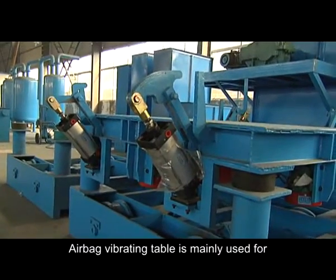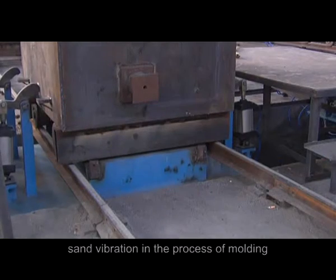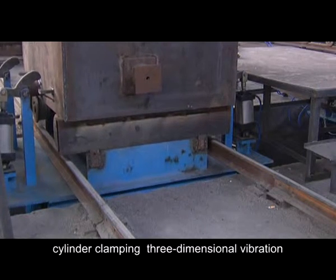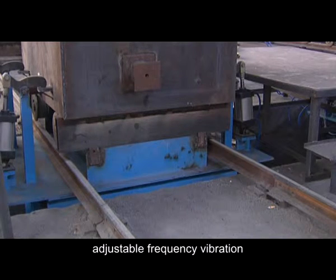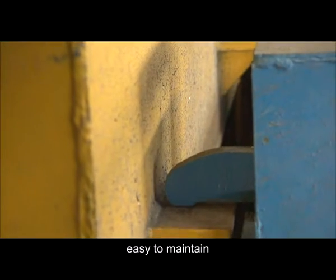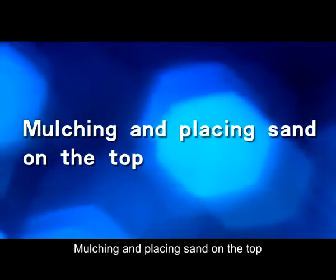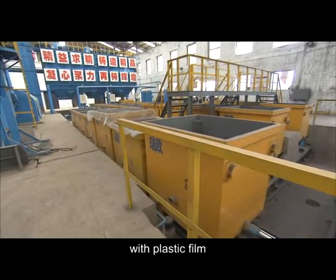Airbag vibrating table is mainly used for sand vibration in the process of molding, with the features of airbag lifting, cylinder clamping, three-dimensional vibration, and adjustable frequency vibration. The vibrating effect is good, and it is characterized by high production efficiency, simple operation, and easy maintenance. After mounting and placing sand on the top, the surface of the molding flask is sealed with plastic film.